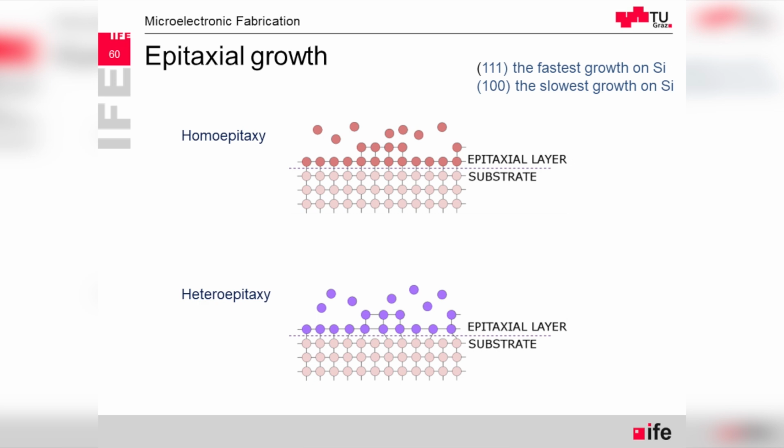And there will be devices which have the layers of germanium or silicon germanium mixture. Even for controlling mobility in scaled technologies, also germanium is used in the channels of either type transistor, also depending if it's holes or electrons mobility, the story might look differently.